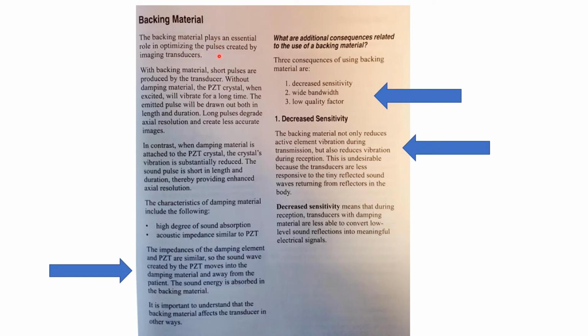The backing material plays an essential role. It decreases sensitivity, provides a wider bandwidth, and a lower quality factor. It has a high degree of sound absorption, and this helps with the acoustic impedance matching so you can get a quality signal.